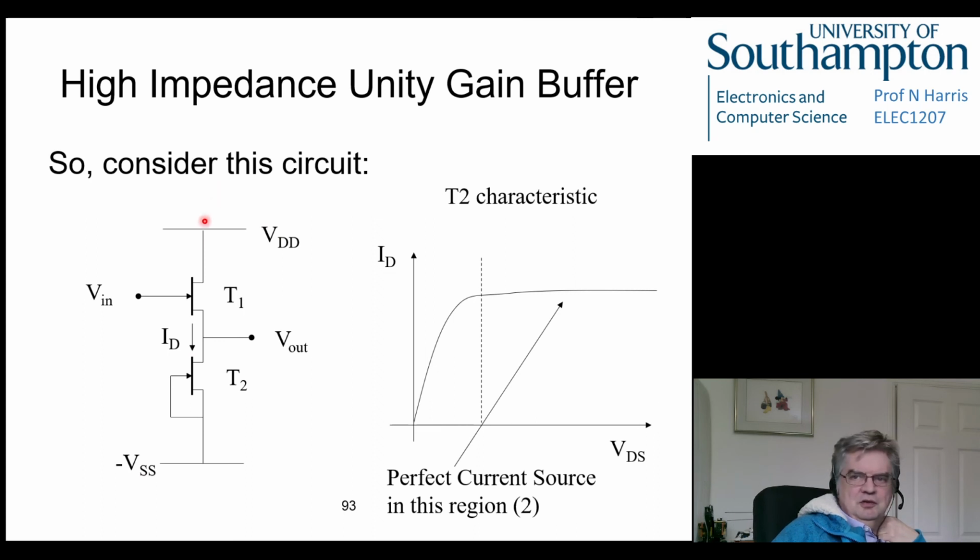Why is VGS 0? Because VGS is the difference between VG and VS. That's the definition of the value of VG with respect to S. And both of them are at the same potential, so the difference between them is 0. Okay? Yeah, in T1. That's the point.